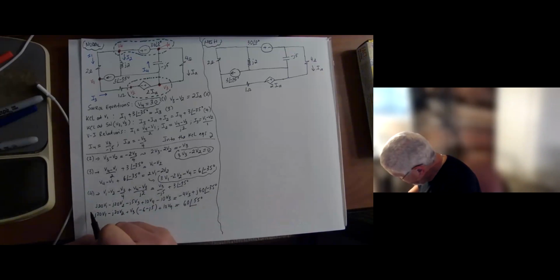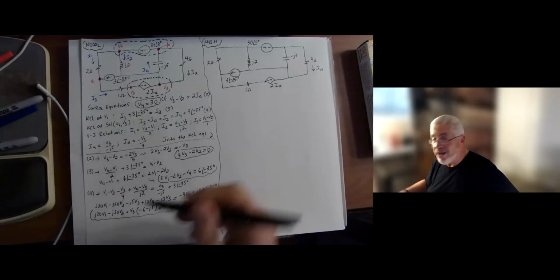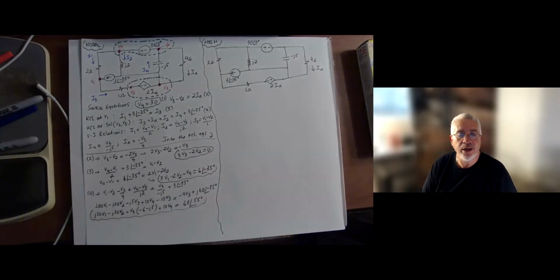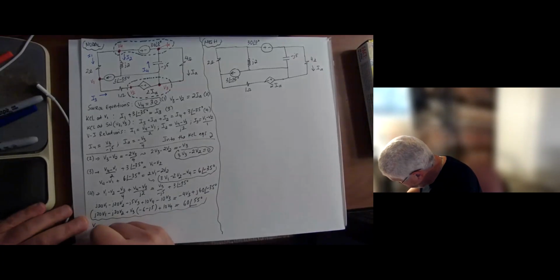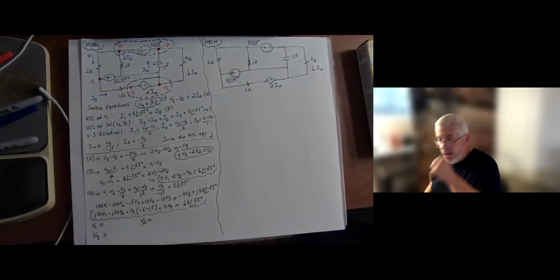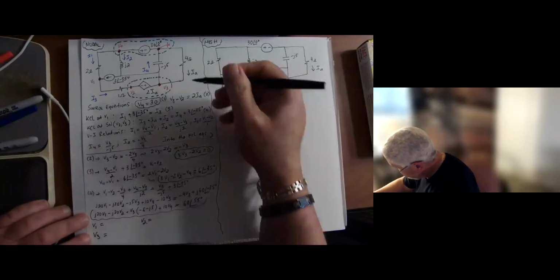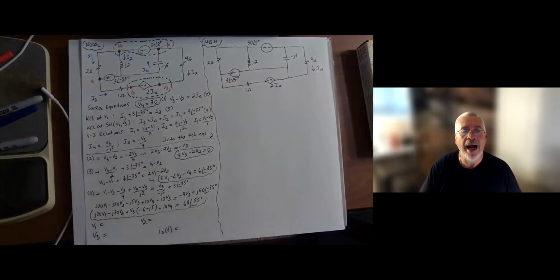Okay. So that is my four equations, four unknowns really. So what I need to do after that, I could put them in a matrix form essentially and solve for V1, V2, V3. And I'll show you the example in a little bit here. And then once I get that, then I can solve for IA. Really, IA is essentially minus V3 over 4, so I can find IA of t. Okay. So I'm going to pause now to just look at these results.